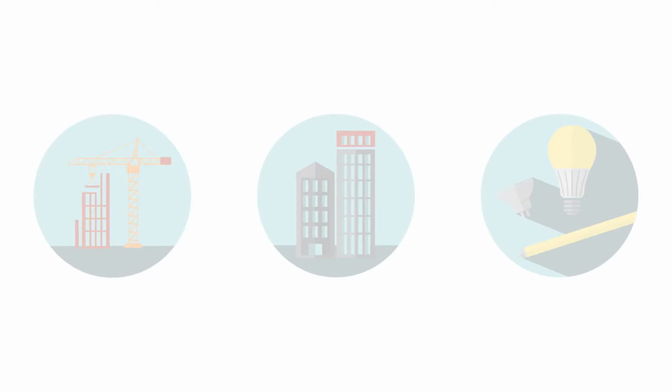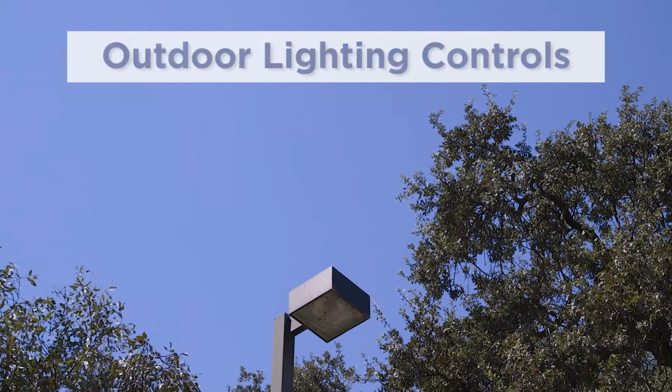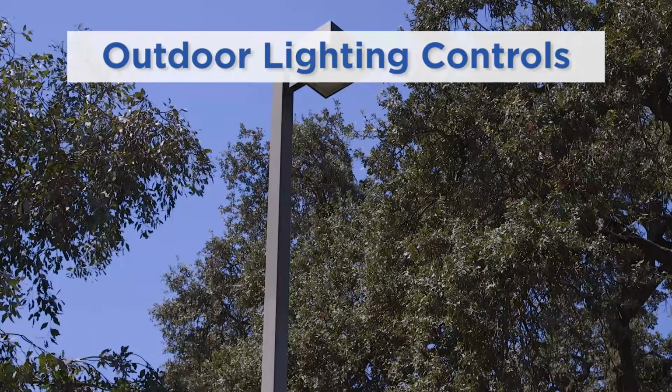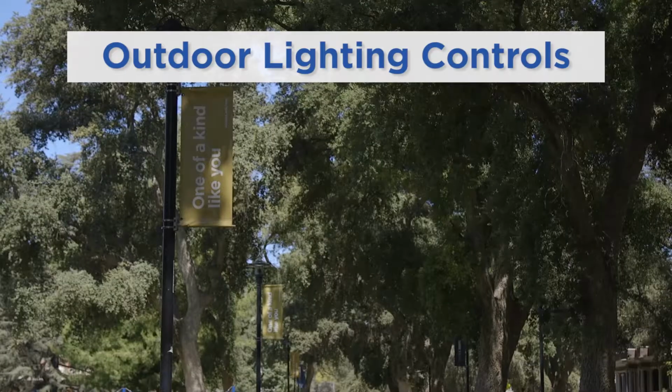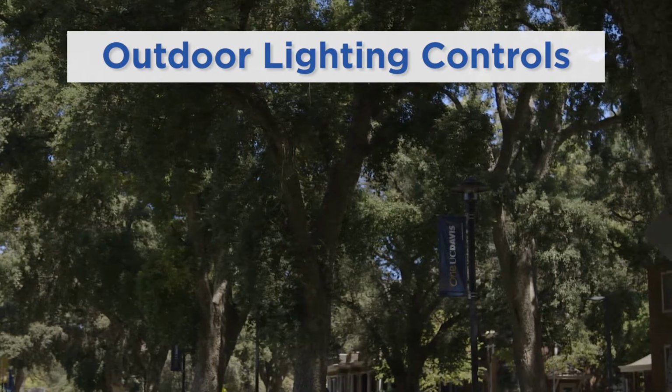Outdoor lighting controls are required for many types of non-residential outdoor lighting systems under the 2016 energy standards. These controls requirements apply to new construction, addition, and alterations projects. Outdoor lighting should always be off during the day. This control strategy is usually achieved using some type of automatic shutoff control, like an automatic time switch control or astronomical time switch control. These control devices automatically turn outdoor lighting on and off based on a preset time schedule.